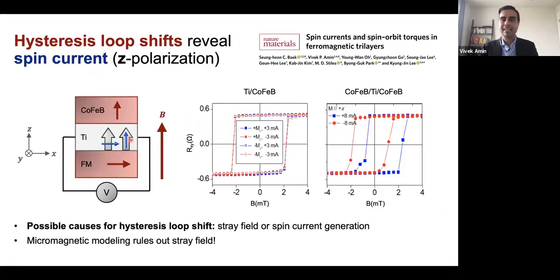If you look at this type of device structure, essentially you're going to need another ferromagnetic layer. Because you have one ferromagnetic layer plus a spacer layer, which is essentially acting like a generator of this type of spin current. But then if you want to read out whether or not you have a 1 or 0 here, you're going to have to add the rest of the out-of-plane magnetic tunnel junction on top to do something like that. Maybe there is a more creative way of reading out what the information is through some sort of spin Hall magnetoresistance or some sort of in-plane magnetoresistance. But either you have to figure that out or you have to add another ferromagnetic layer.